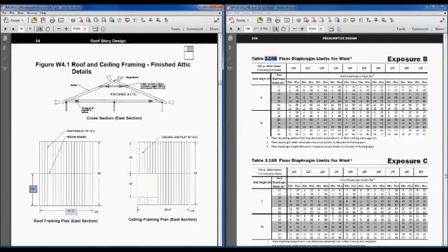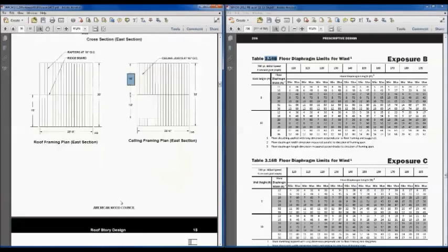And this part of the finished attic is about 25.5 feet along the 40-foot length. Then we've got that stair opening right here. That's only about 12 feet long, and if you recall, we've got some limitations on diaphragm openings. We're within those limitations with this 12-foot limit. Our ceiling joists, which are also doubling as floor joists, are at 16 inches on center, and again, they span that 16 feet to that load-bearing wall. And so that's our ceiling joists and our rafter spans.